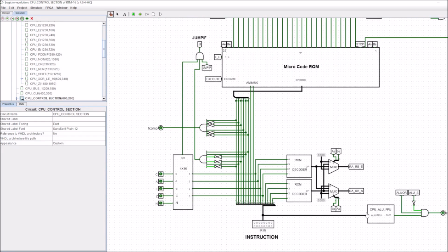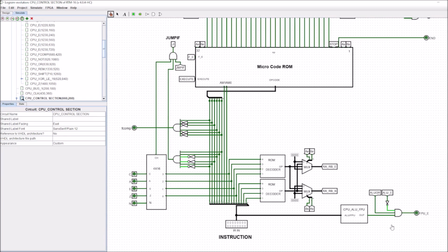Now, if this is a floating point unit instruction, then this line here is going to go high. But that's not the only thing that we want to check. We want to actually wait until we have the choice of the floating point unit function. So the floating point unit function would be a value 1, 2, 3, 4, 5 for add, subtract, multiply, division and square root. And there's a sixth one there which we'll talk about later.